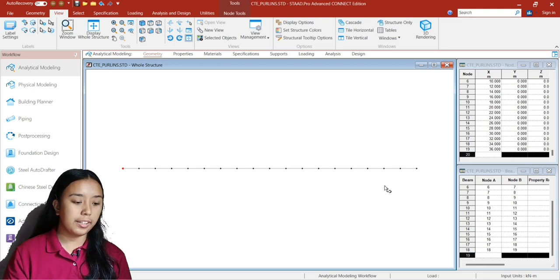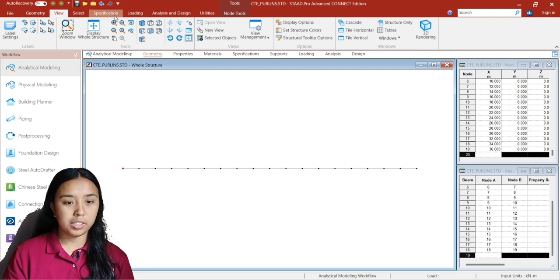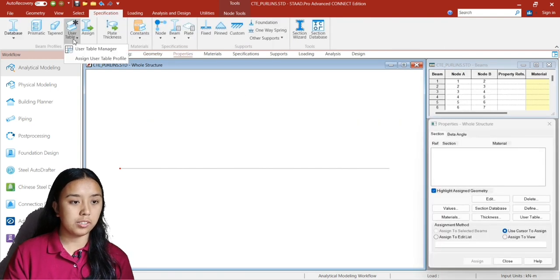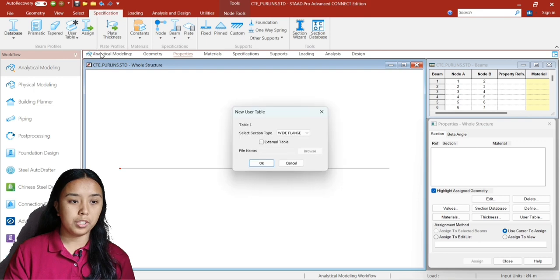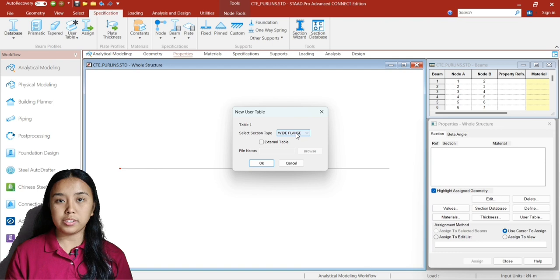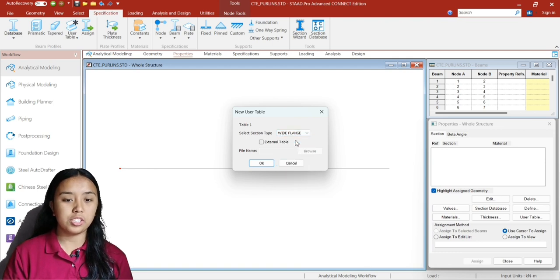Now, we will create its section. So, to create the section, let's go to specifications, user table manager, and then, since it is a purlin, we will use channel.